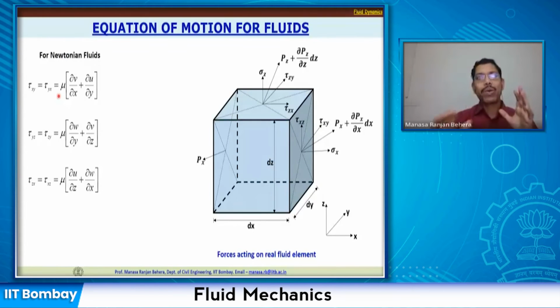So if we write down the equation for tau xy, it is going to be mu (∂v/∂x plus ∂u/∂y). It is not only due to this, because the total shear is due to two different components, v as well as u on this face. Okay. Now in the plane that is perpendicular to z, you have tau xy or tau yx, isn't it?